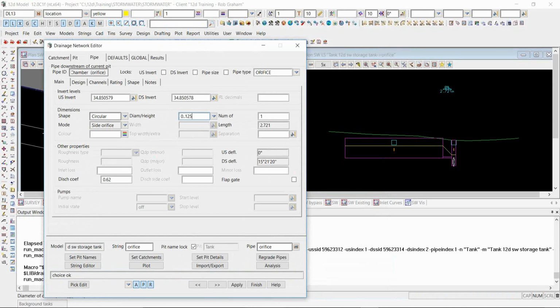At this point, you've probably realized that, yes, I have run this before and taken a look at it. The guesses I'm using for my sizes are ones from some past experience on this model. So if you were doing it the first time, you might have to guess once or twice what better values would be used. So the idea there is I'm making the orifice bigger. That's going to get rid of the water quicker.